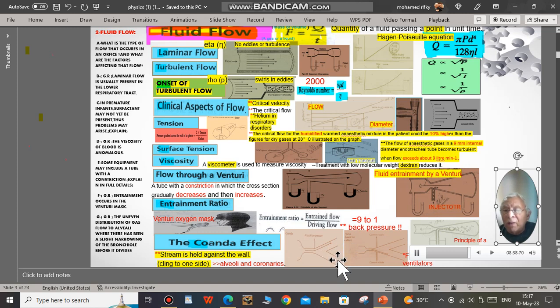Of course, it also occurs in the upper airway. We can use this decrease in pressure at this area by using a flow through this narrowing part, where we can direct the fluids upwards and downwards, creating what we call a valve. A valve, of course, we can use in a ventilator. This is what we call fluid logic in ventilators.